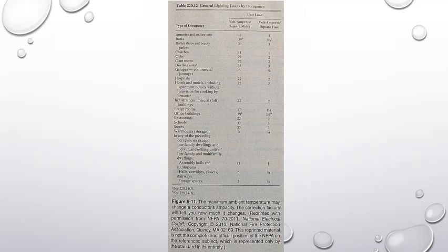The ampacity of 71.4 amps divided by the 0.76 correction factor is 93.9 amps according to Table 310.15(B)(16). A 4 AWG conductor with a standard rating of 95 amps is required to deliver the 50 amps.